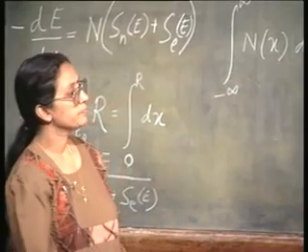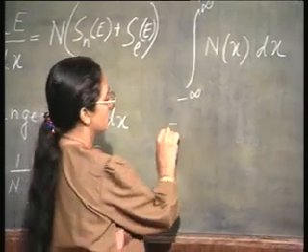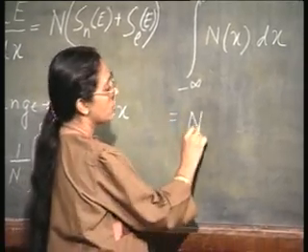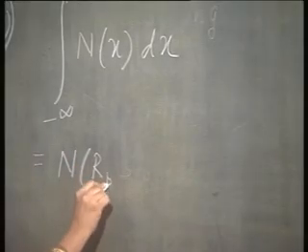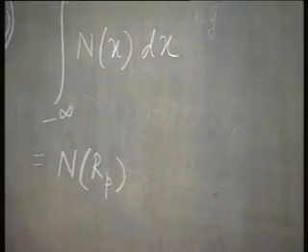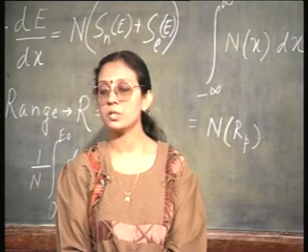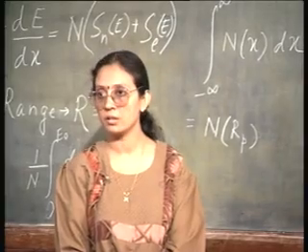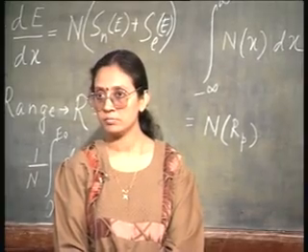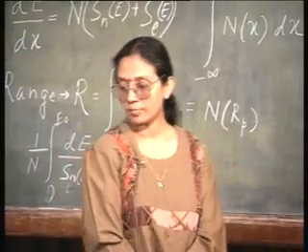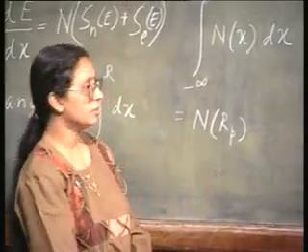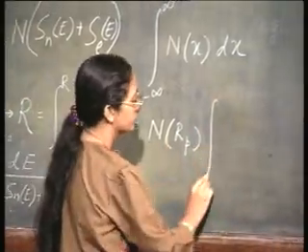So, what do we get? See, the peak concentration is a constant. It does not depend on the distance anyway. This is where the maximum number of ions are coming to rest, so it is not a function of distance. Rp, you know, is only dependent on the energy. So, this is something I can take out of the integral, and then what I get is